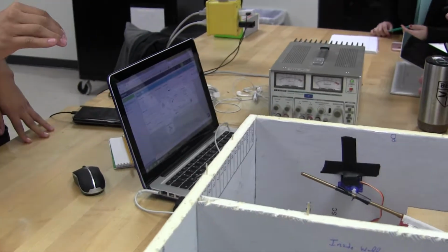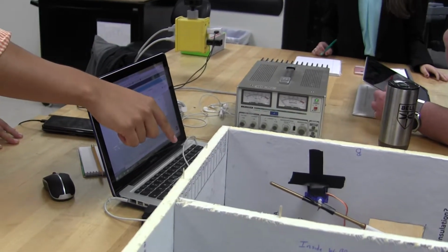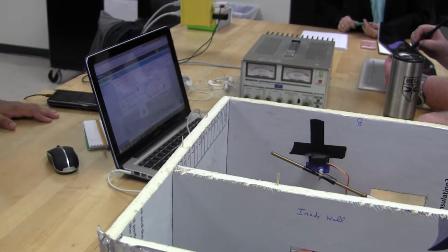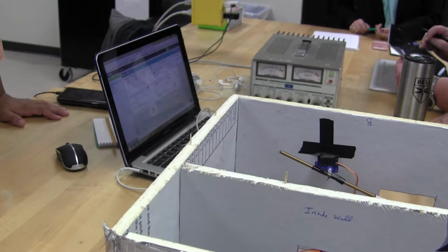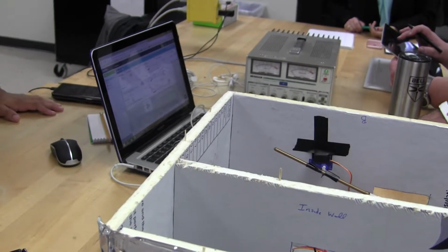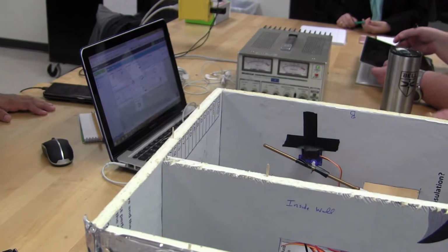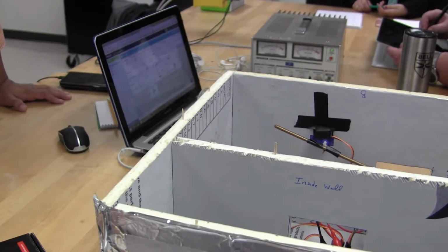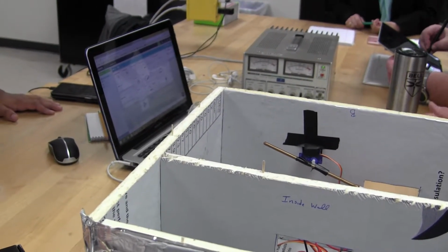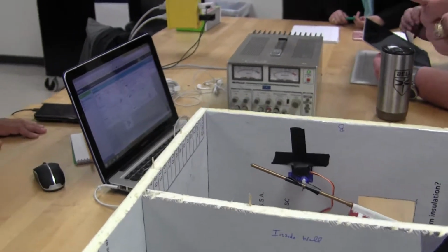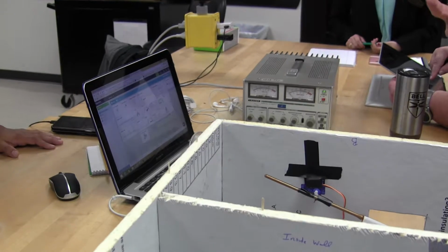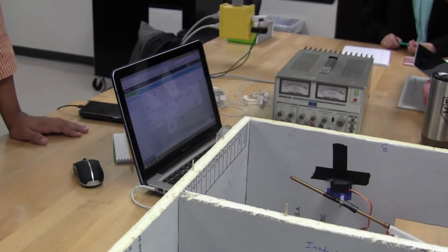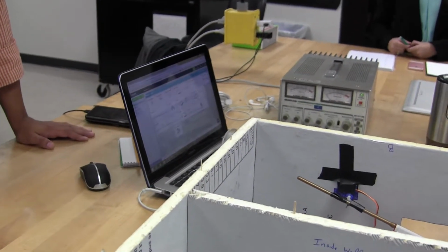So specifically, when one of the rooms asks for a change, if I'm in a room and I ask for change, that should go to my heating cooling unit and tell it whether I want heat or cooling. That's going to be based on the ambient temperature versus the set temperature. So I'm only going to have either cooling on or heating on. But each room opens and closes their valves, flappers, to allow air to go into the room to change its temperature.